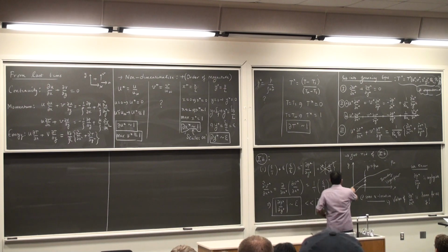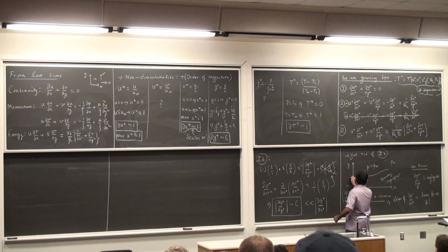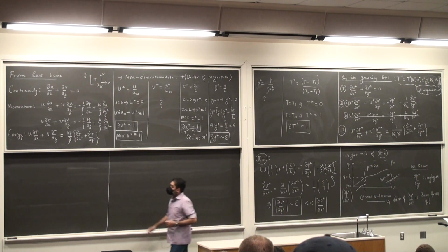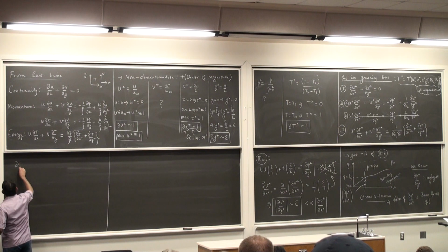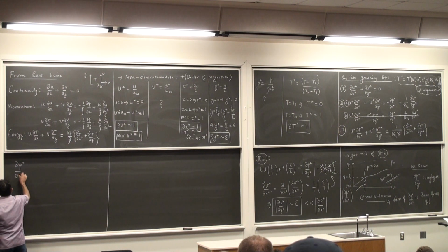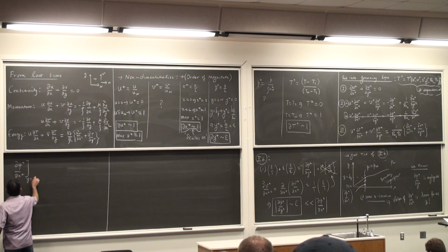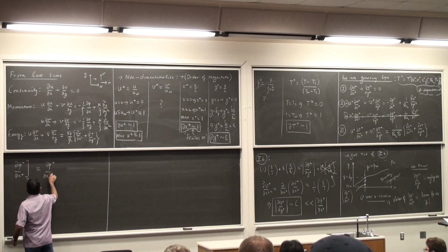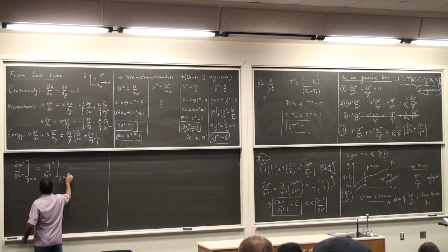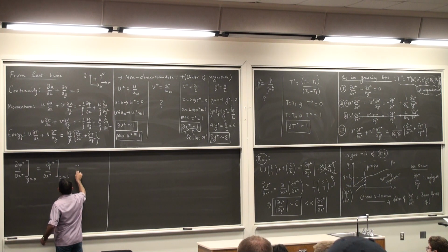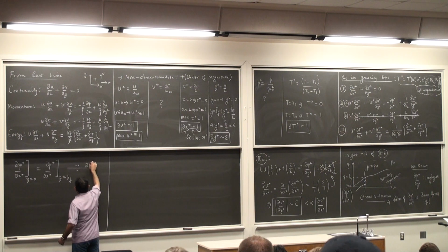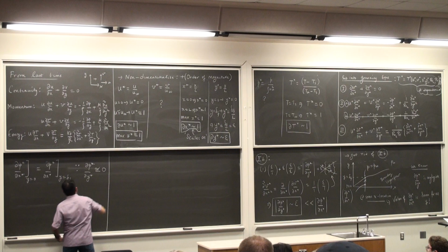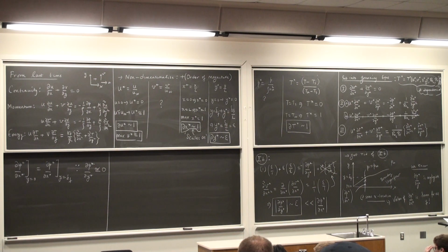So this is y is equal to 0. Y is equal to delta f. So dp star by dx star at y is equal to 0 is the same as at delta f, because dp star by dy star scales as epsilon, or this is very, very small. Okay?